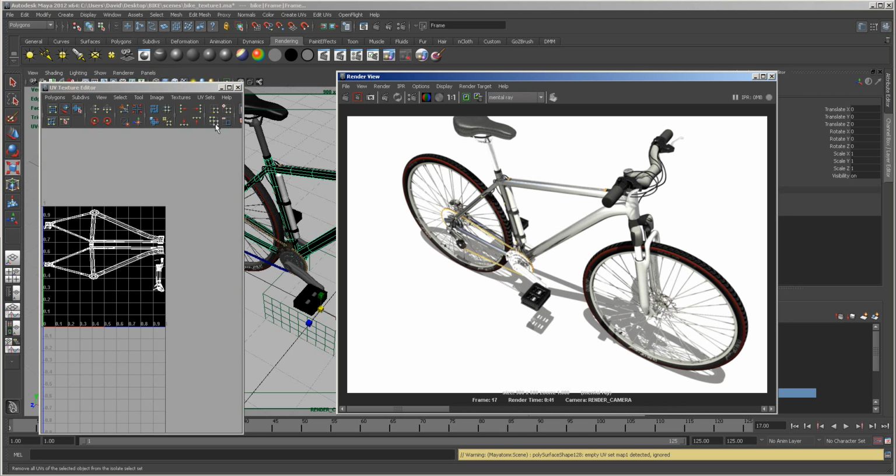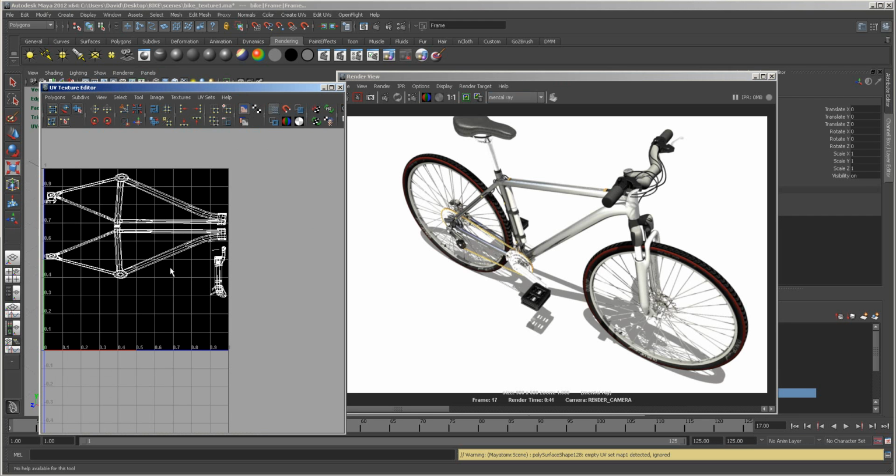So at this stage I would say that for all those areas that you want to be in these colours in the right position, I would do it all with the Lambert test shader, just to check that everything's working okay. And then I would set all your UVs up, and then take it across and plug it into the mental ray paint pass that we just did.